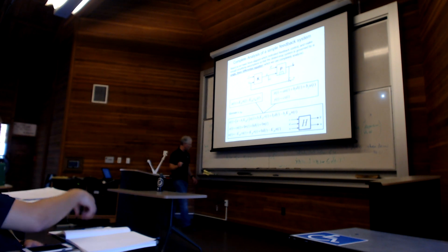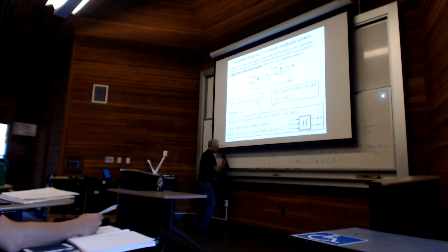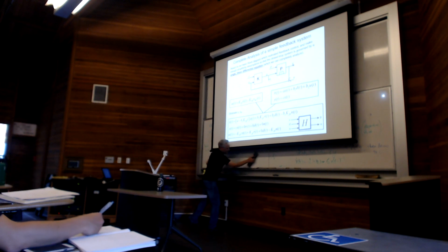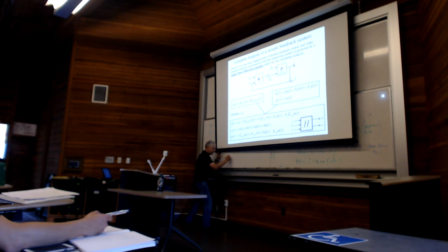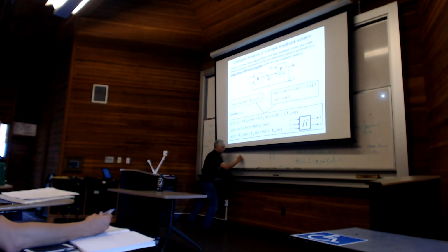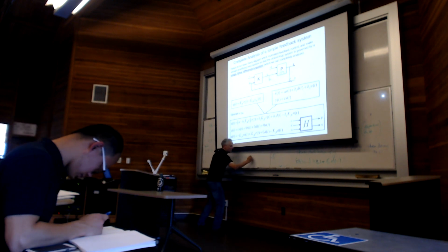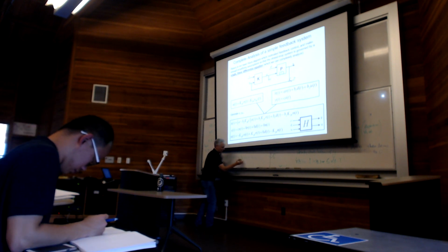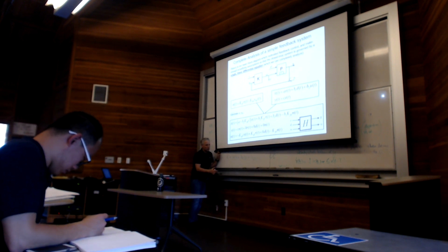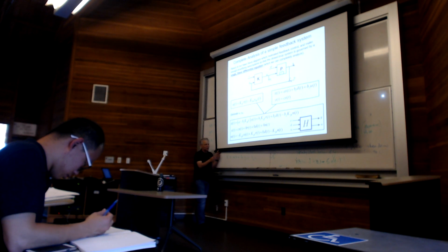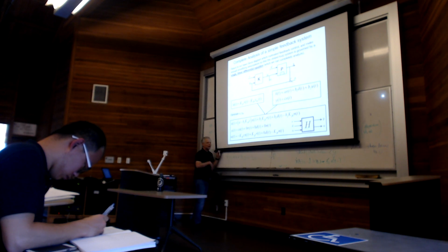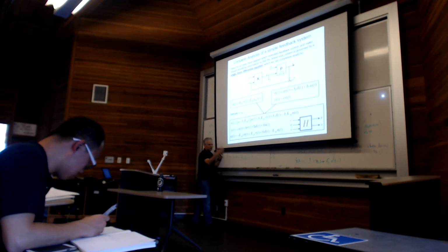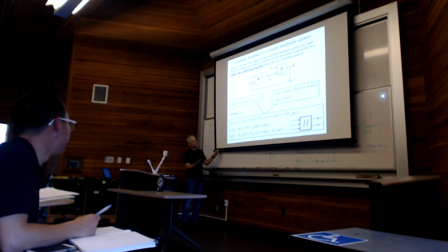Remember how we talked about early on, if I had several inputs, so now I'm backing up to just the abstract setting: X dot equals AX plus B1 U1 plus B2 U2, right? 2 separate inputs. Well, we saw that the effect of these together is really just the additive separate effect. We can look separately at how U1 affects X, and then how U2 affects X, and the way in which their combination affects it is just the sum. So we really can treat these things separately.